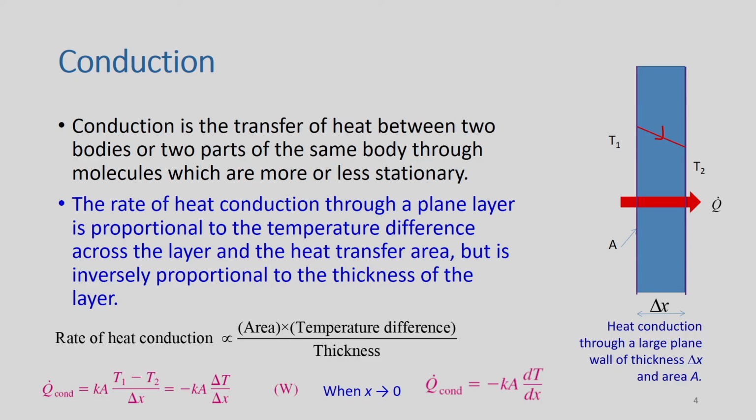The rate of heat conduction through a plane layer is proportional to the temperature difference across the layer, transferring from T1 to T2 in this block, and the heat transfer area through which heat is conducted, but is inversely proportional to the thickness of the layer.